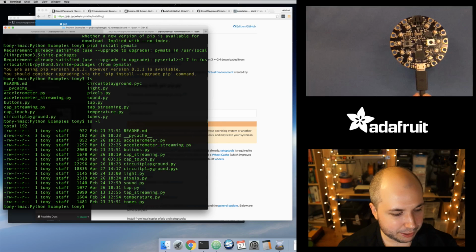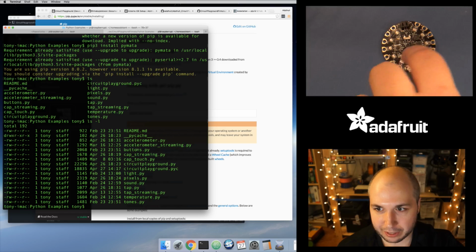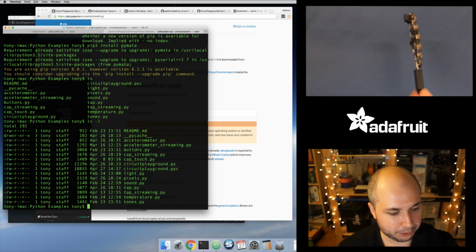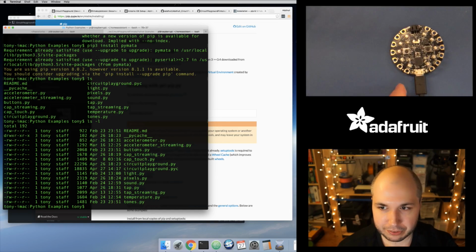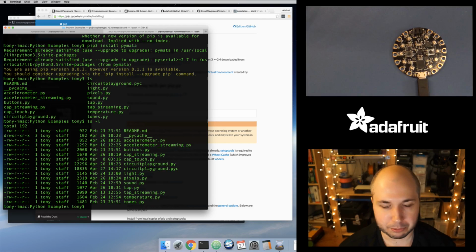And so you can kind of tell, okay, when the board is held in this orientation, the down axis is the z-axis, and so I should see the z-axis as 9.8 meters per second squared. But when I hold the board in this orientation, now the y-axis is the up and down axis, and so now that axis is 9.8 meters per second squared. So, some basic ways to sense how this thing is being held just using an accelerometer like that. So that's what those demos do.